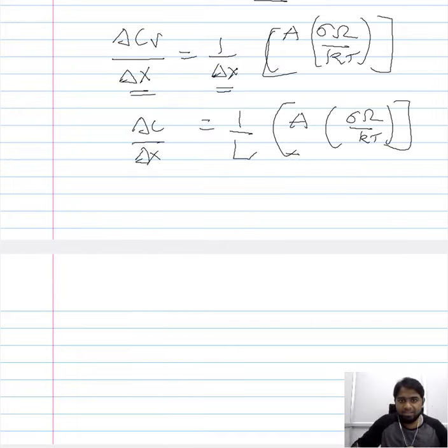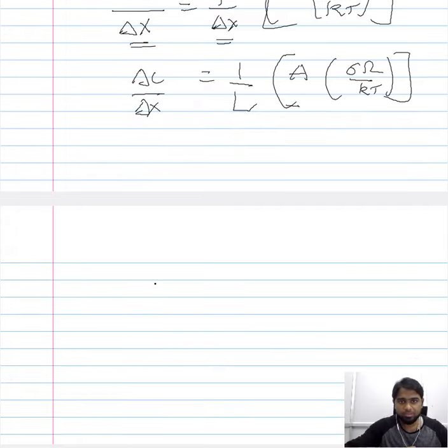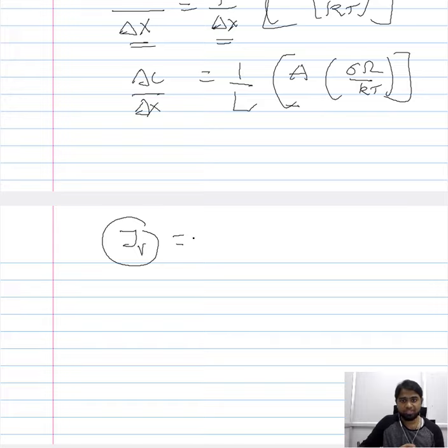The reason we have translated it to the gradient is because we want to consider the formulation of the flux of these vacancies, because the flux of the vacancies is what governs the climb, that rearranges the dislocation, and that enhances the plasticity. So for that, we need to consider the flux of the vacancies, which is nothing but minus D, the diffusivity of the vacancies, times its gradient.